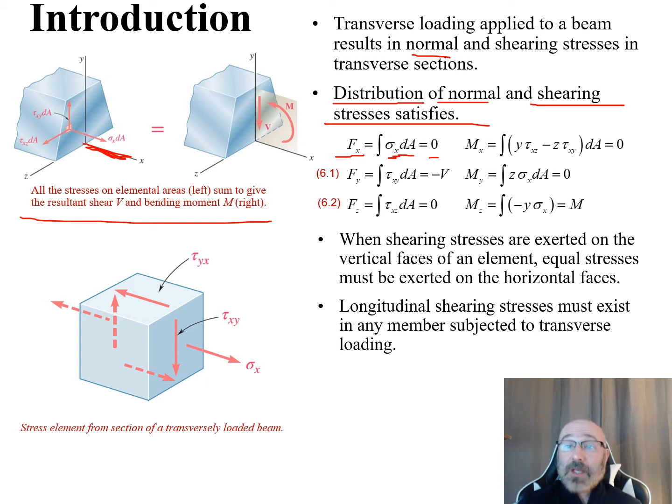And then we can, at the same time, in the x direction, take a look at our moments in the x direction. So what moments do we have acting in the x direction right there? Well, that's the summation of all these individual ones right here. So that's what our integral is right there. So we have now our y times our shear stress in the xz direction. So let's take a look. Here's our shear in the xz direction right here. So this is going to be our moments about our x-axis, times this perpendicular distance right there.